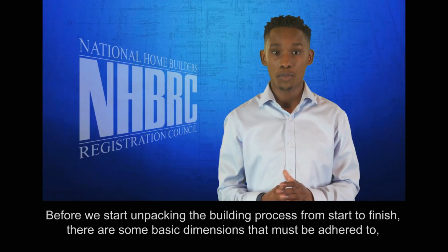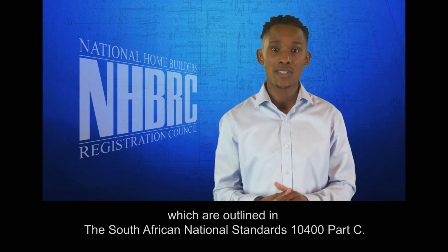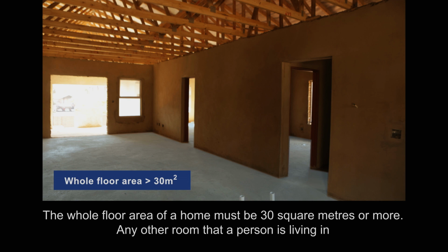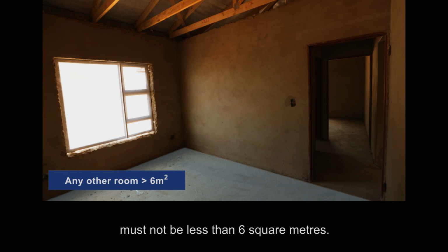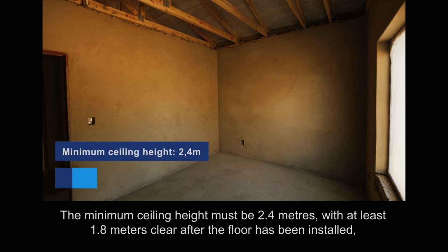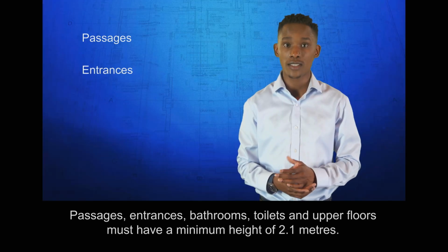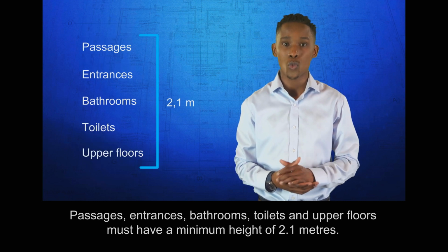Before we start unpacking the building process from start to finish, there are some basic dimensions that must be adhered to, which are outlined in the South African National Standards 10400 Part C. The whole floor area of a home must be 30 square meters or more. Any other room that a person is living in must not be less than 6 square meters. The minimum ceiling height must be 2.4 meters, with at least 1.8 meters clear after the floor has been installed over an area of 6 square meters. Passages, entrances, bathrooms, toilets, and upper floors must have a minimum height of 2.1 meters.